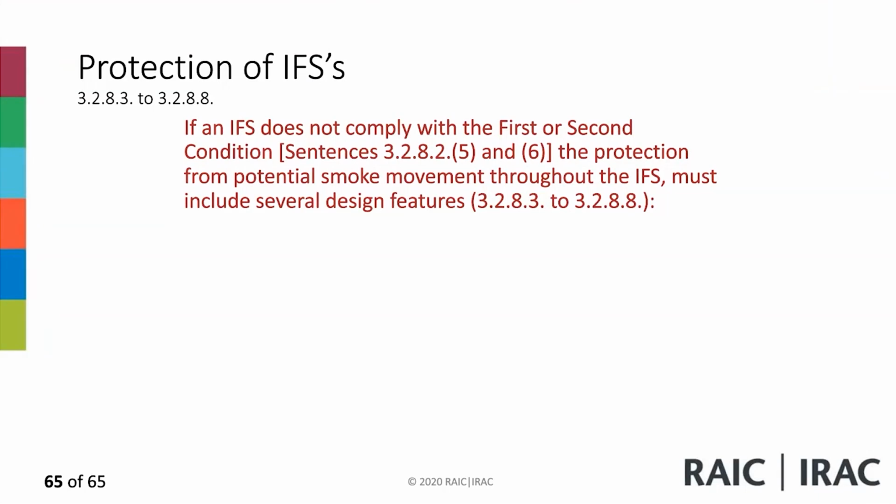And then we have another one, 3.2.8.2.4, an interconnected floor space in a Group B Division 1. This is for detention. Occupancy need not conform to the requirements of 3.2.8.2.3 and 3.2.8.2.8, provided the interconnected floor space does not interconnect to more than 2 adjacent stories. So if you have 2 stories in a detention area, and this is Article 3.2.8.2.4, you can allow the interconnection of 2 stories, but not more than 2. This is for group B1 occupancies.